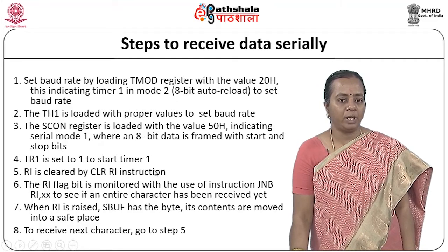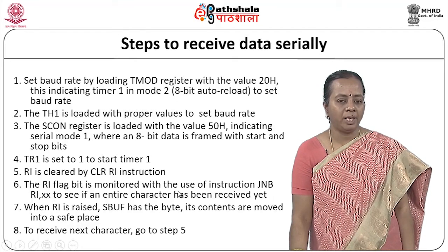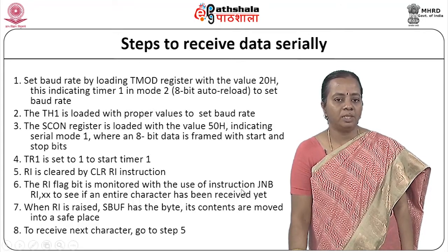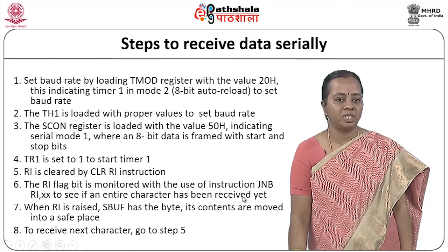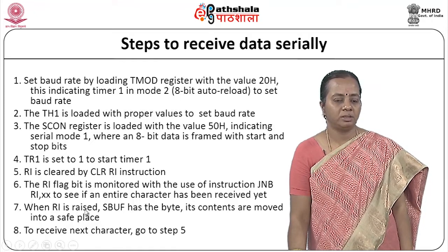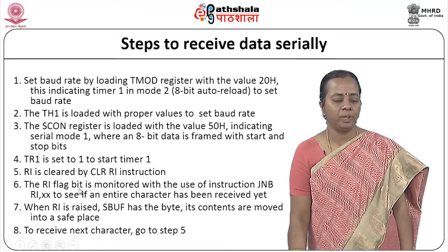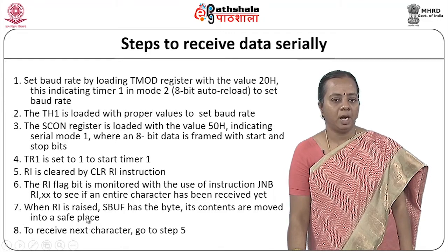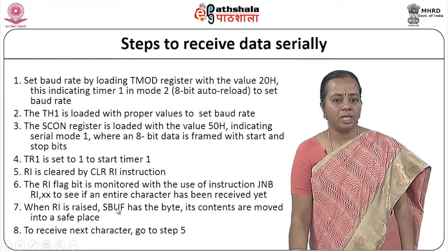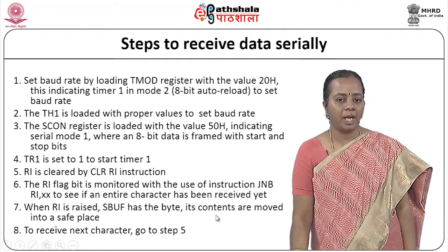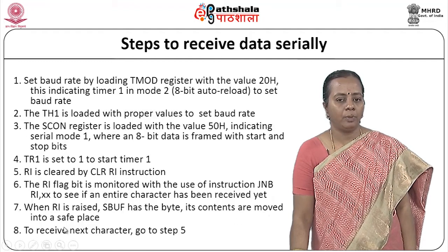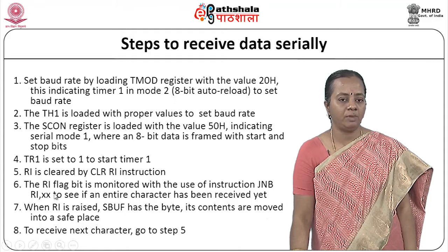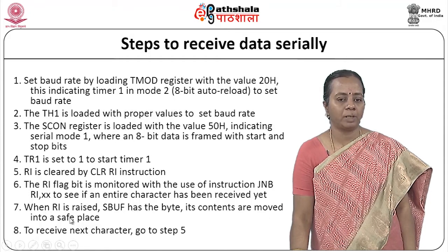Now the serial communication is started. Now we need to monitor the RI flag, which says that if it is equal to 1, then SBUF has received the whole data. Till then we have to be in an indefinite loop. Once RI is equal to 1, SBUF has a byte, and these contents are moved to the destination place we need, where you can move this SBUF value.